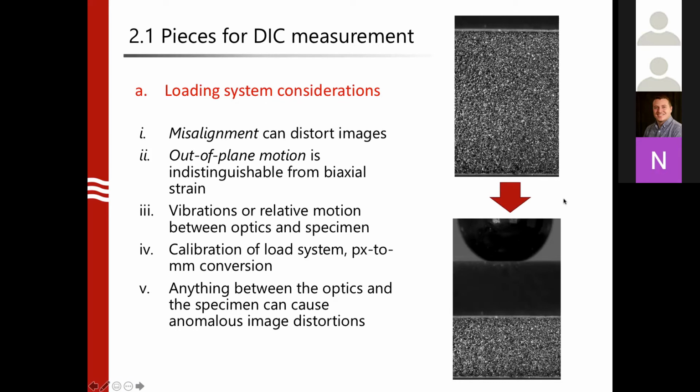Basically, what you want is a reference image, and after the loading, a deformed image. This deformed image looks nice, not blurred, and the change of the image just reflects what the real deformation is. So then you are good with this loading system setup.